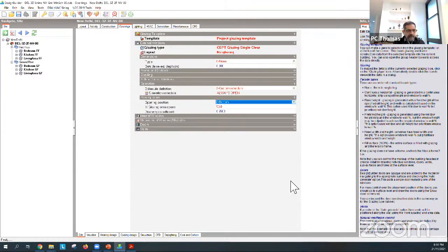They don't open windows like we open in India. Okay, I'm going to leave it as left because typically in India we have shutters which open out, so we can open a fair bit of the window. I'm going to allow 50% of the window to be open. Okay. The discharge coefficient, if you don't know any better, that's fine. Okay, so I'll leave it there for now.